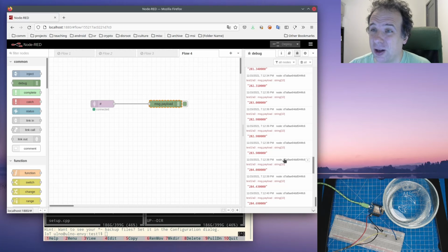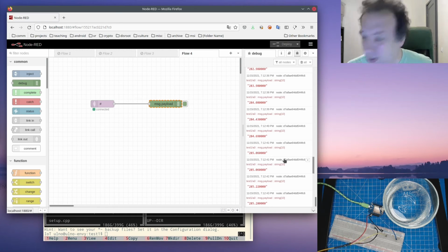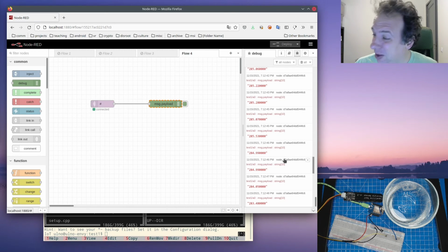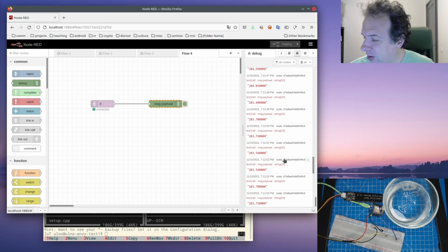So if you see values which skyrocket to 1023 here, then you might have to consider a voltage divider. So be careful. But this is how you can connect the capacitive soil sensor. Just two 10K resistors can do the trick. Maybe if you use slightly lower values and do a little more testing and measuring, you can get it to span the 0 to 1023, 1 volt range that the ESP8266 can measure. But this is totally fine for testing whether it is wet or not.